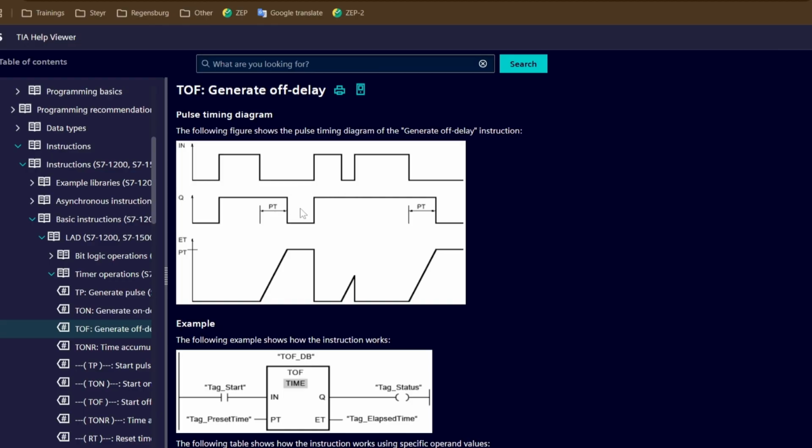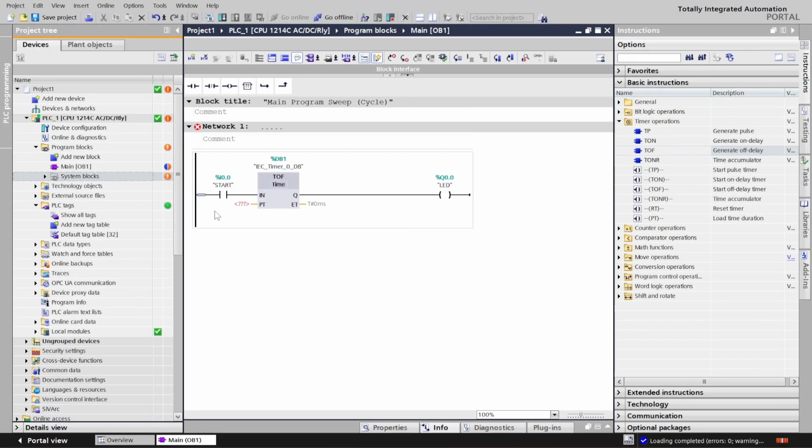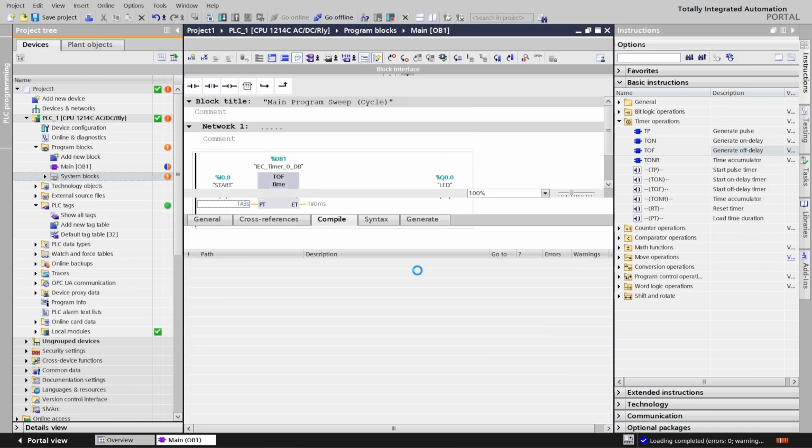And in the second scenario, when the input is on, and after 1 second, you press the input again, and our preset time is 2 seconds, let's say, the input is off for less than the preset time, so the output will stay on continuously until the input is off for the preset time. Let's go demonstrate it. Yeah, let's make it 3 seconds. Download it.